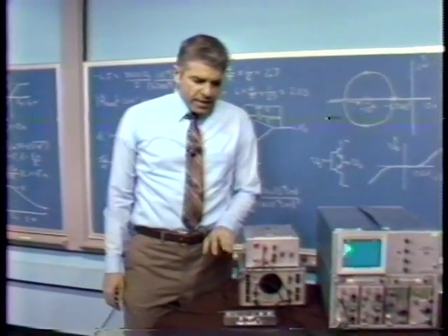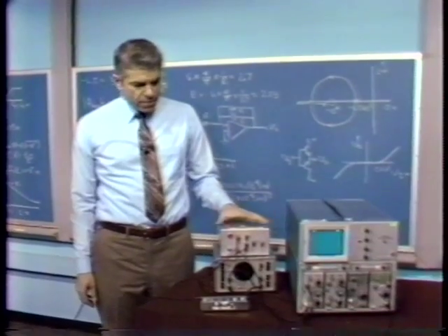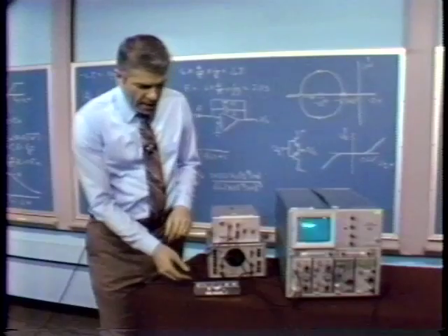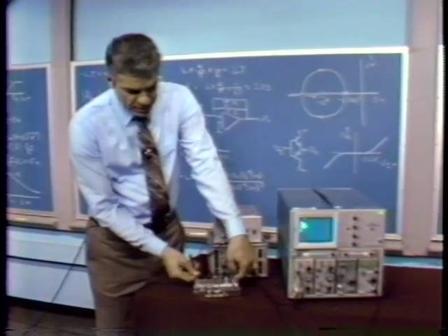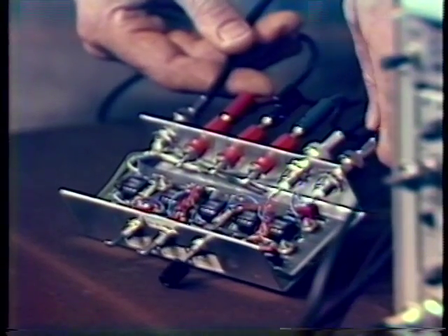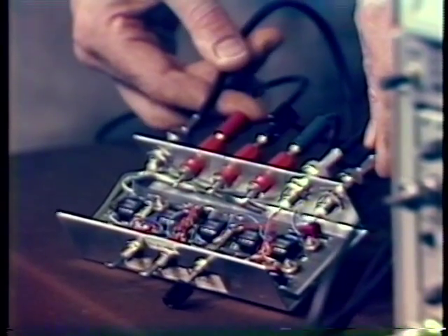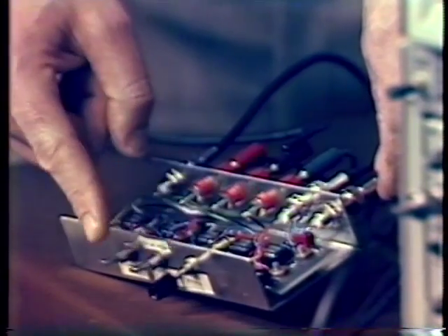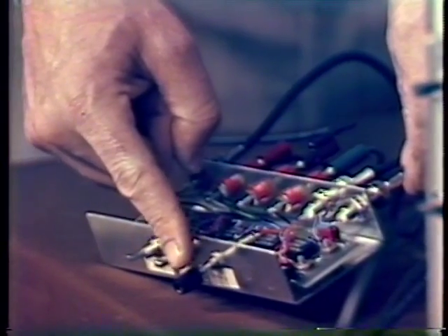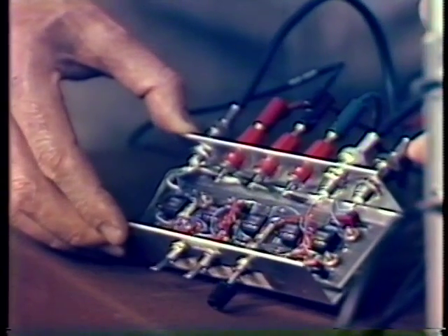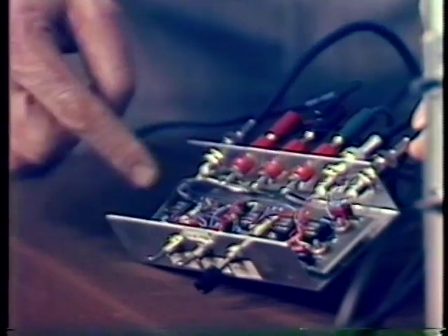What we have here is, again, the usual test generator, a power supply to power our setup, and we have the actual conditionally stable system here. We see 5 operational amplifiers ganged up, so they perform the functions that we showed in the actual schematic. We have the potentiometer that varies the magnitude or the gain, the quantity A0. We have a couple of switches that I'll ignore for a moment. We'll see what their function is later on, but this is the basic box.